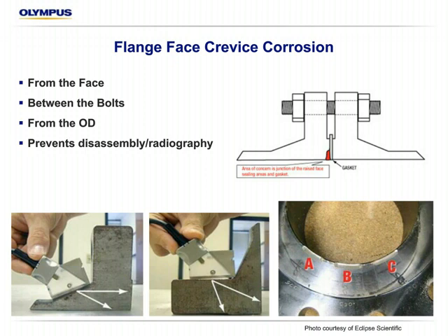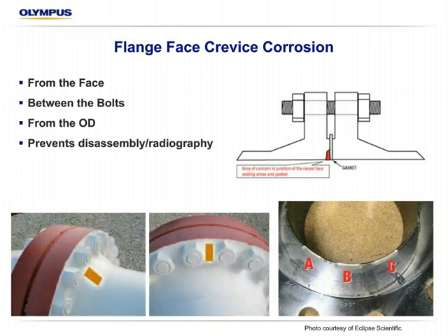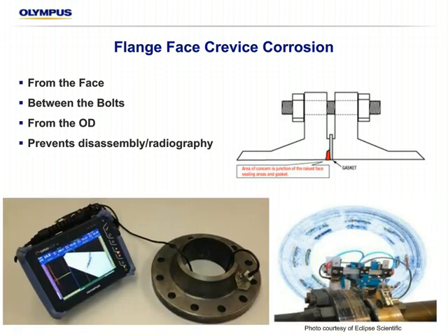You can usually see the amount of corrosion, but you're going to say it's classified as ABC or 10, 20, 30. You're probably still going to take apart the ones that you do see a good amount of corrosion. But it is extremely helpful to avoid the radiography and then to prioritize your NDI, especially during shutdowns and turnarounds. You can take them from the bolts or from the lip, depending on the configuration of the flange face. It's more illustrative of what the ultrasound is doing there. And there are some third-party solutions out there that actually can scan from the top of the flange as well.